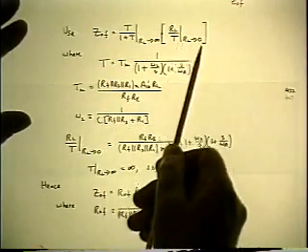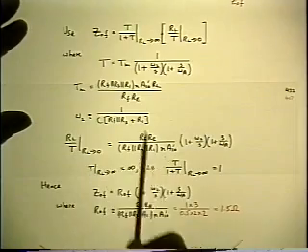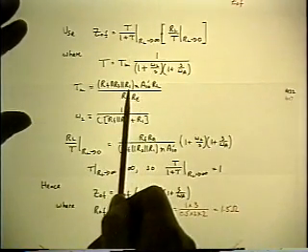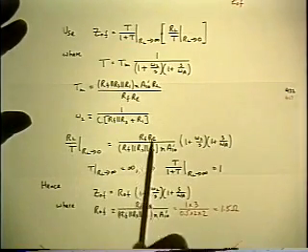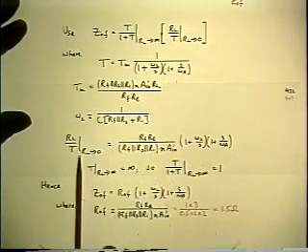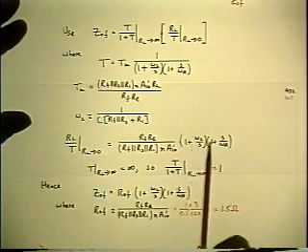Let's evaluate the limit with RL going to 0. So I have to take RL over T. So that's RL over Tm. And the Tm is proportional to RL, so it will cancel. And then I have the two corner frequencies for the T, and the two poles of T will be zeros of this function.